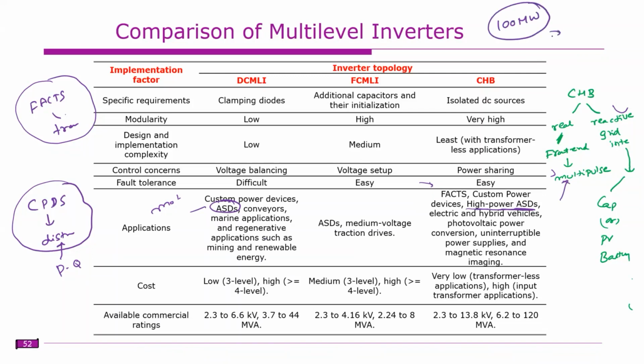You also require it for lift irrigation projects. For example, we have the Kaleshwaram project, that is a lift irrigation project, where you have motors with a capacity of 30 megawatt, and we have some motors in the 50 megawatt range. Okay, so all these motors are coupled to a cascade H bridge inverter. So if you want some control of motors, that is connected to a cascade H bridge converter.